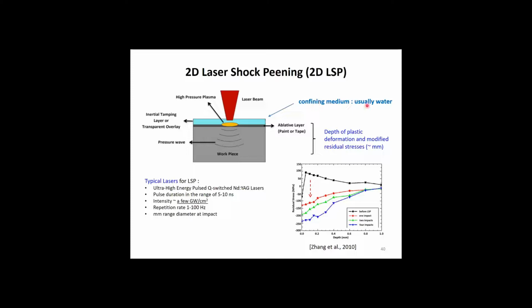Okay, so the confining medium here is typically water. It's transparent to the laser, but at the same time, it prevents the shock waves from going upwards. So that means the maximum goes down into the material. That's what we want. Now, in doing that, it's known that you create plasticity, and the plasticity itself creates compressive